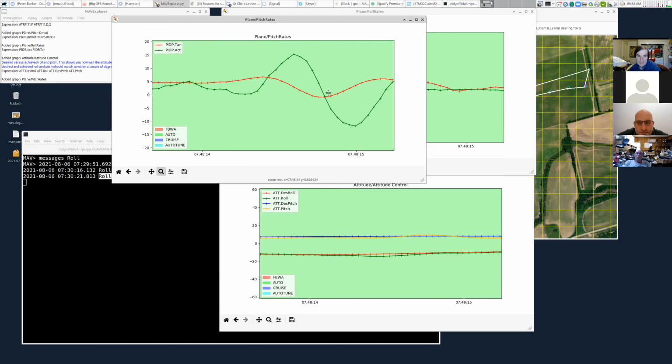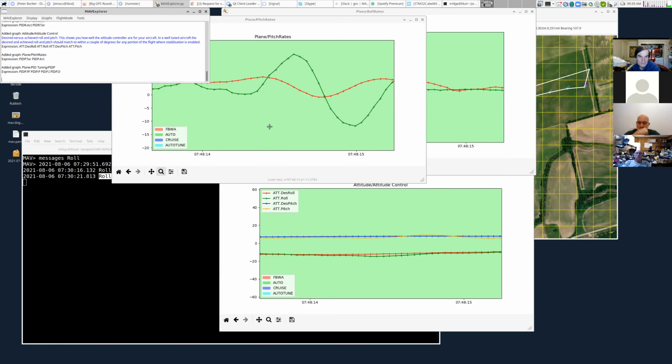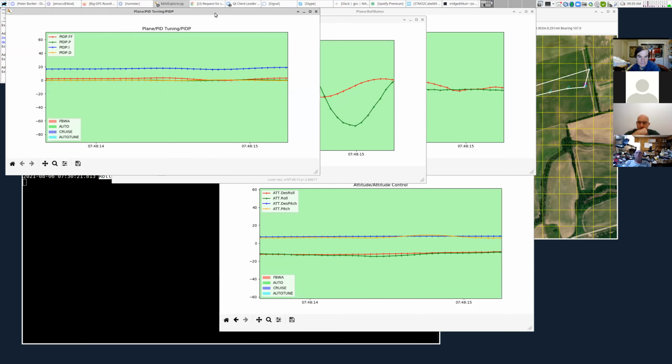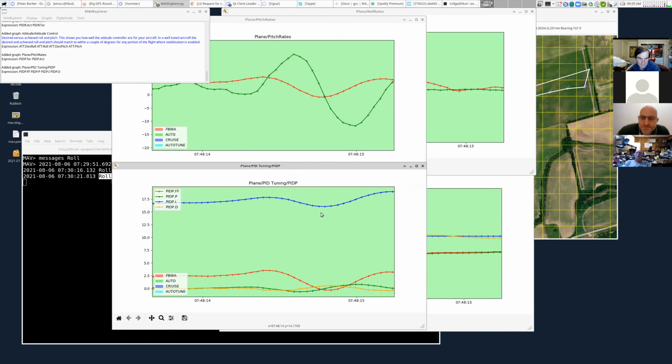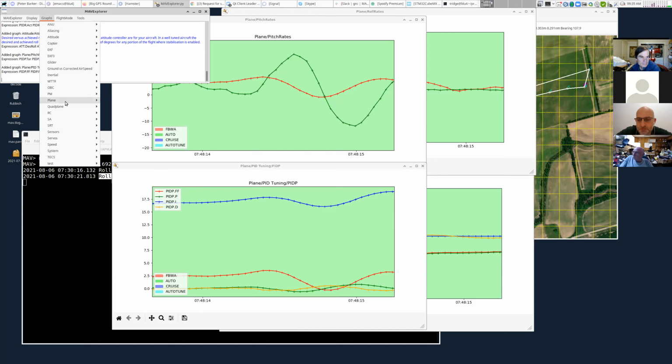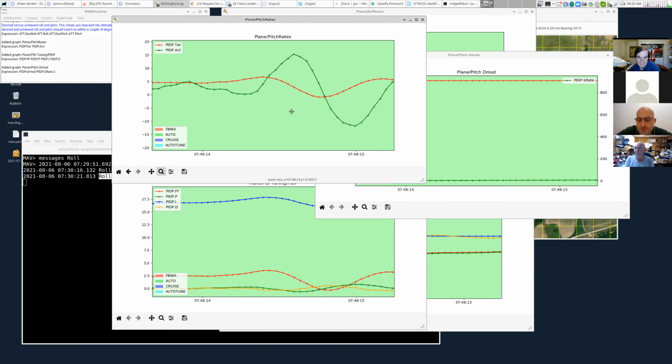Paul? I think it, yeah. So something that also shows up there, you can see that when you get this disturbance in the measured pitch rate, it pitches up, it hits a bit of a gust, for example, and you can see that the demanded pitch rate is then going down, because the angle control law, which says, what's my demanded angle, what's my measured angle, I'm going to demand a rate, is saying, oh, I need to put the nose down. It's demanding a nose down pitch rate, and then the pitch rate swings back the other way, because it often does that with a gust response, and then you can see the angle controller sort of trying to catch up with it.